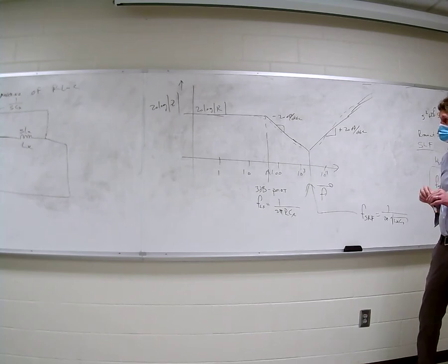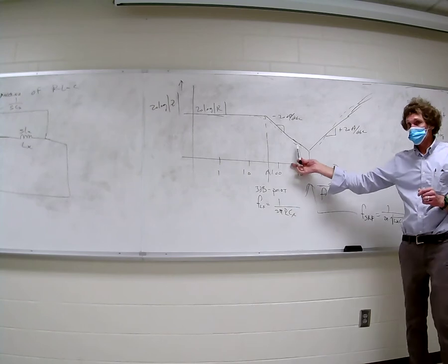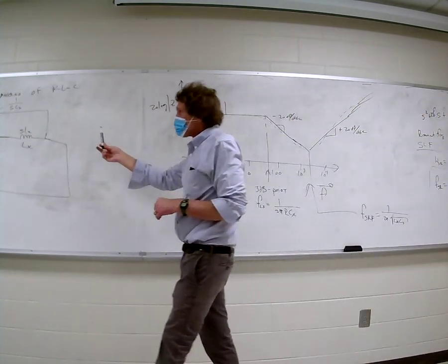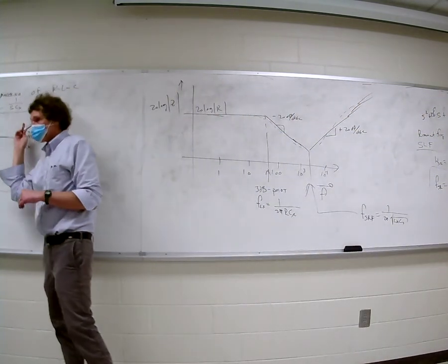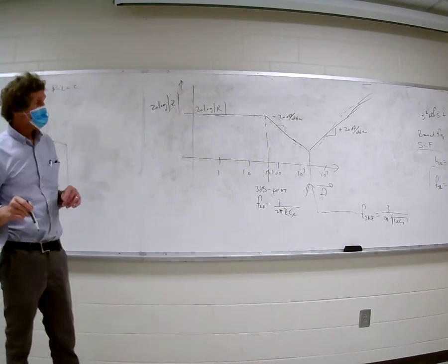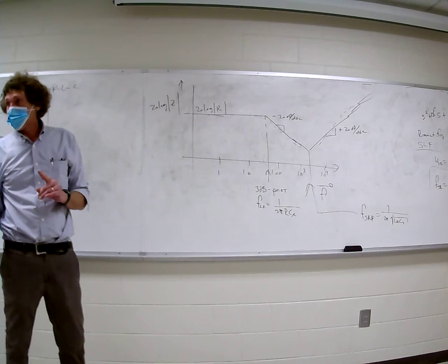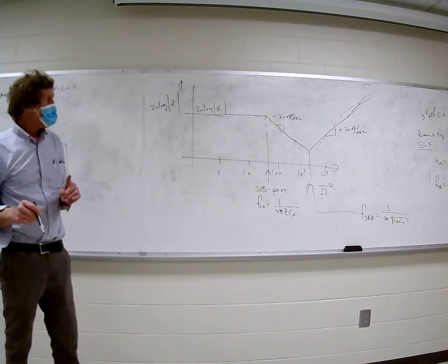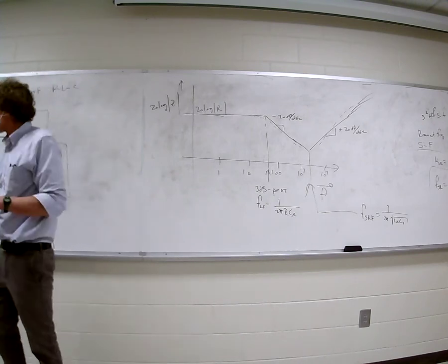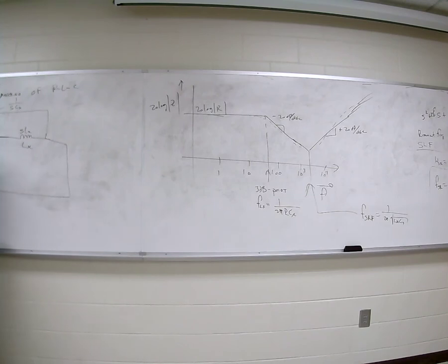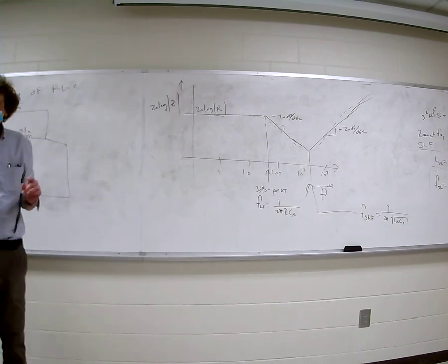Which means that at first the parasitic capacitance kicks in. That's this pole right here. It starts bringing it down, and then it hits a self-resonance and starts going up. Now you might say, well, Dr. Dubinsky, if I take this equation from different Rs, Ls and Cs, I don't get that.